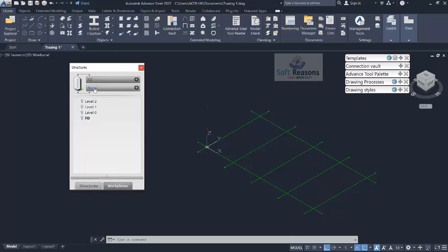You just have to select in these provisions and then select level 0, which is the bottom constraint of the steel stanchion we are going to be placing. For the top constraint, you select the upper part of this provision and select level 1. So we are placing a column between level 0, which is the bottom constraint, and level 1, which is the top constraint.